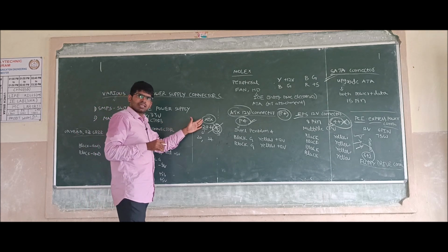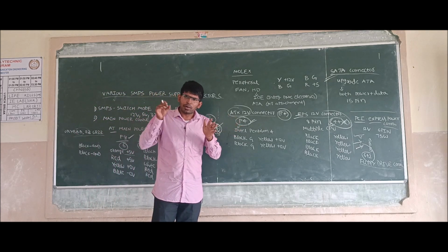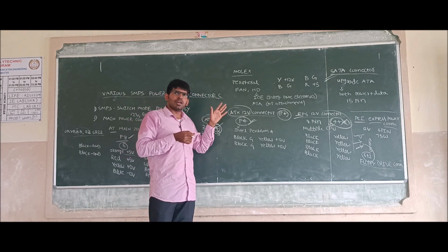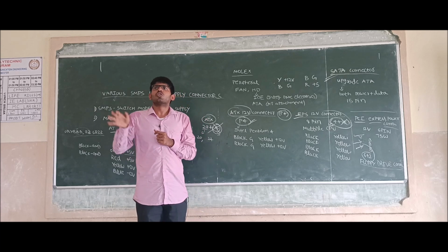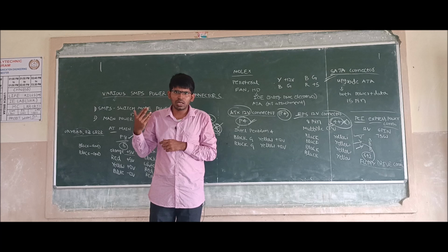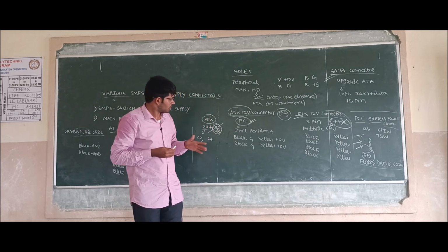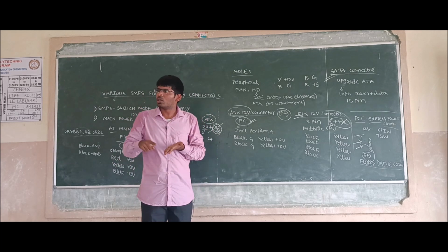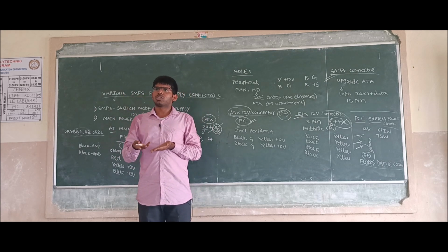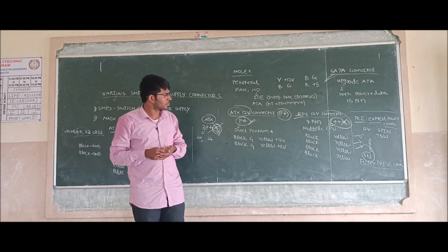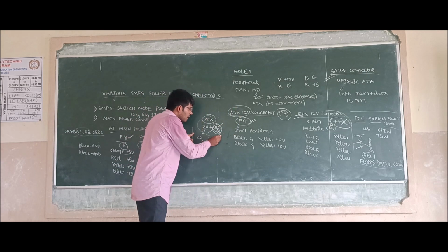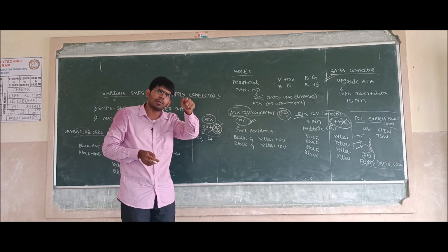Later ATX, the ATX motherboard, to power up this ATX motherboard, how many pins are we using? 20+4. Either we can use 20 pins, that was the old board, or we can use the 24 pins. In these 24 pins we have 12 volts, 5 volts, 3.3 volts, -12, -5. To power the processor, we are using these 20+4 pins, or we are using an additional power connector.